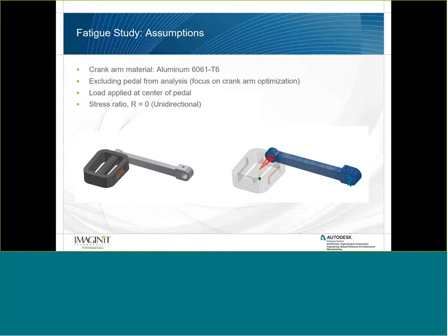I will be applying the load at the center of the pedal, so I'm offsetting that load to where it's being applied at the center of the pedal. This will take into account some of the bending and twisting that will occur as a result of where that load is being applied on the arm.